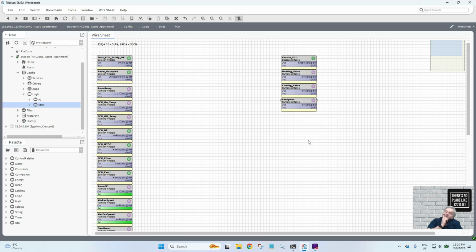A lot of inputs there, and let's be honest, we're not going to use all them inputs, they aren't normally used on a fan coil. But I can't think of anything else. Now you can get fan coils with controllers already built in, like a Distech controller, Tridium controller, Trend controller, Trend Eco.